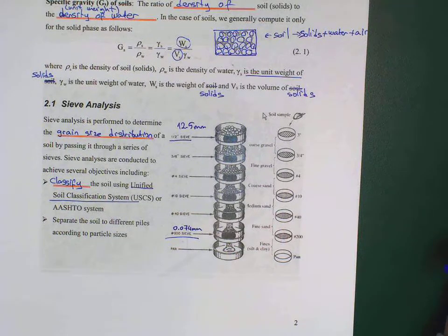As I said, there are different combinations of what you are seeing here. But when you have a combination, let's say we have 10% from the silt and 90% from the sand, we have to give a name to it. We call it silty sand, and silty sand has a certain symbol, SM.